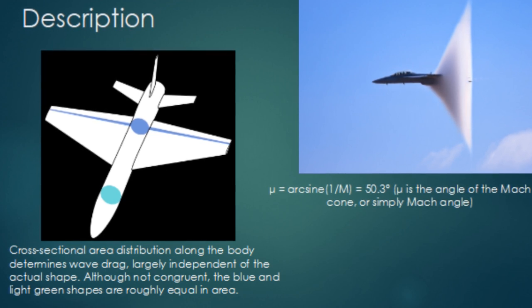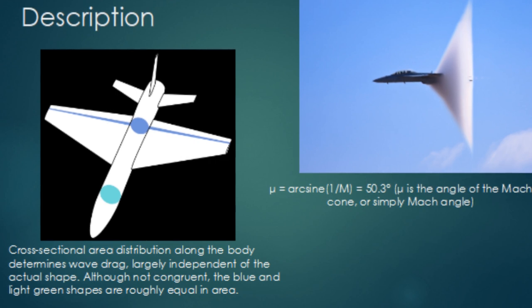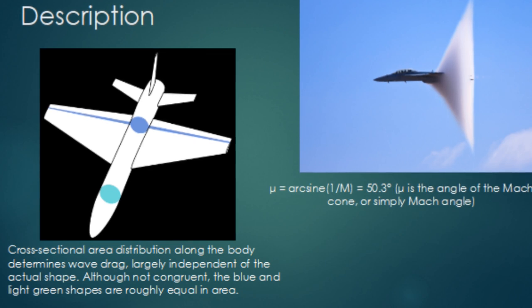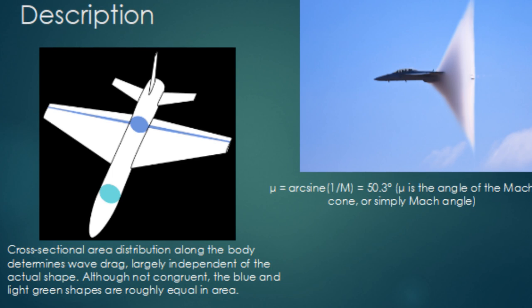As a result, the aircraft have to be carefully arranged so at the location of the wing the fuselage is narrowed or waisted so that the total area does not change much. Similarly, but less pronounced, fuselage waisting is used at the location of a bubble canopy and perhaps the tail surfaces. The area rule also holds true at speeds exceeding the speed of sound, but in this case the body arrangement is in respect to the Mach line for the design speed.